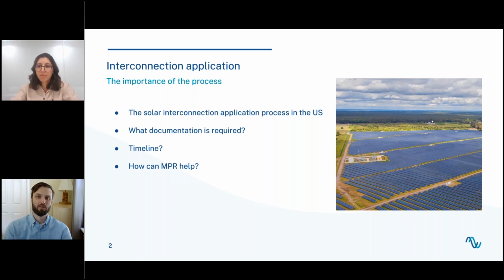We had to use spreadsheets and do a lot of estimation and calculations. And so I reached out to Rated Power and said, hey, in your design, you have all the cable lengths, you have all the cable sizes, etc. Can you implement the WECC guidelines and automatically calculate the collector system equivalent impedance? And working back and forth, I'm happy to say that Rated Power created those values. And so now, as part of the system design, we get a lot of the data and documentation that we need in order to submit an interconnection application. The last pain point that had to be hand calculated, the collector system equivalent impedance, is now rolled into this automated design process.